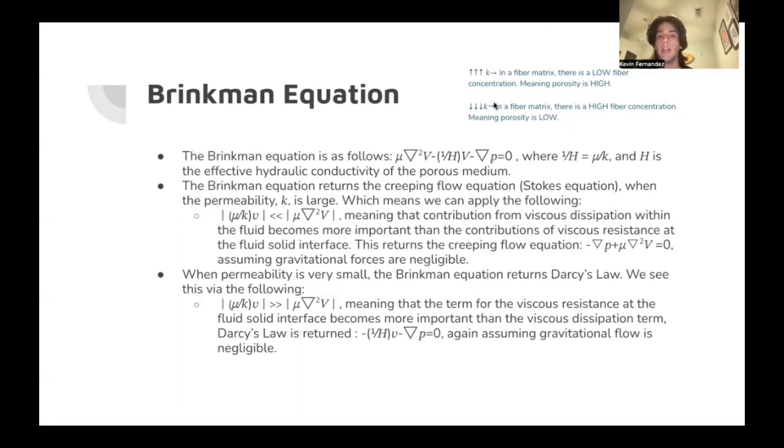On the other hand, when K is low, when K is small, that means that in the same fiber matrix, there's now a high fiber concentration. That means that the fluid flow is very hindered. There are a lot of interactions going on between the fluid and the solid.